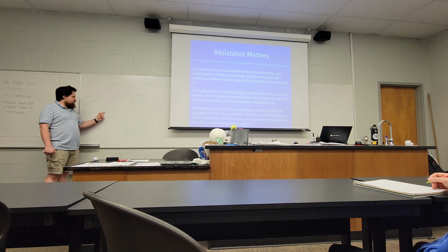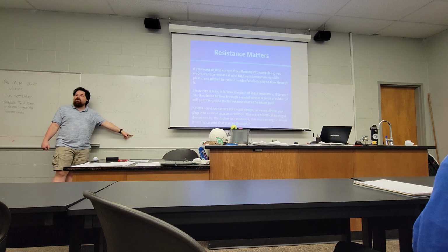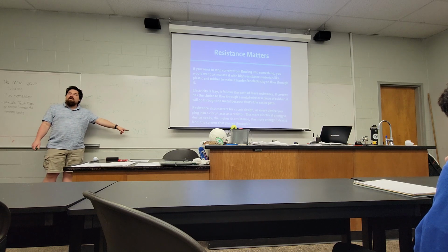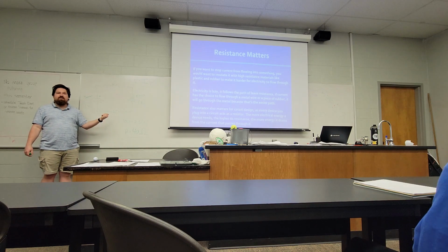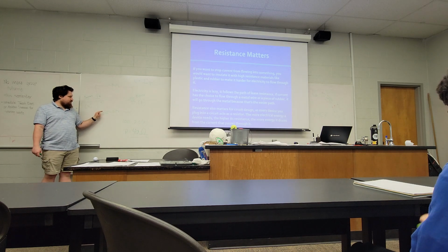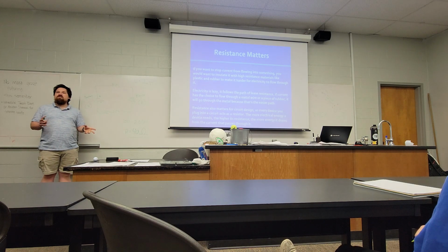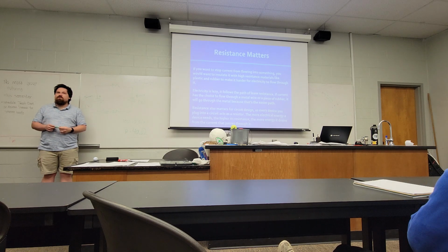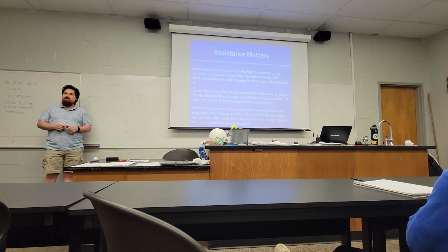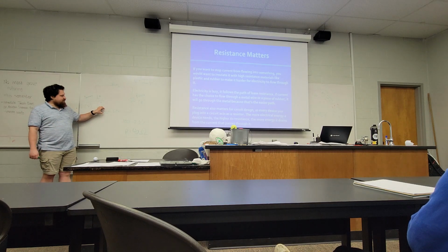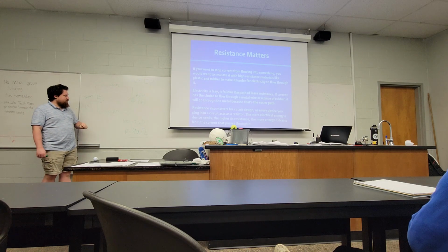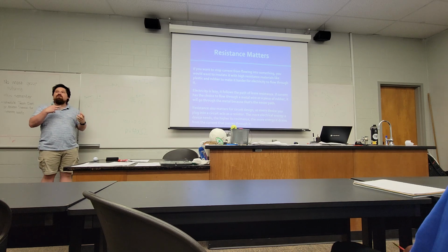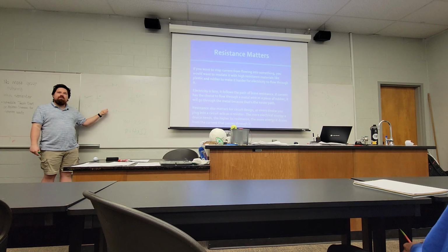So these metal wires have a very small amount of resistance, as we just calculated, meaning that the electricity wants to flow through that. If we coat the wire in rubber having a resistance of hundreds of thousands of ohms most of the time, because it's not easy for current to flow through that, even if I am touching the rubber cable that the wire is encased in, the electricity is not really going to want to jump out of the wire through the rubber and through me, because it would have to jump through 100,000 ohm rubber cabling in order to do that.